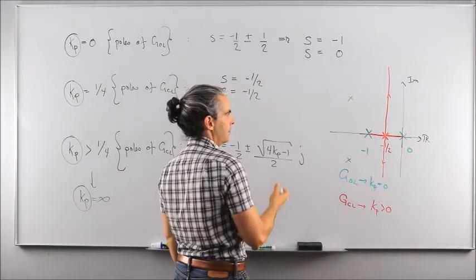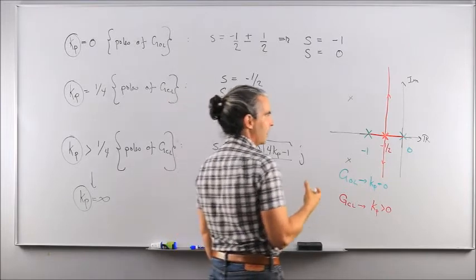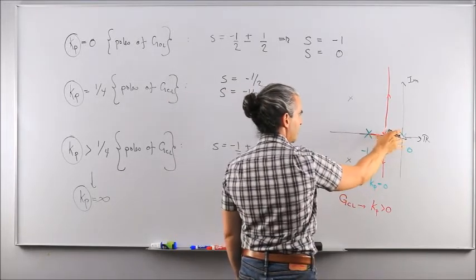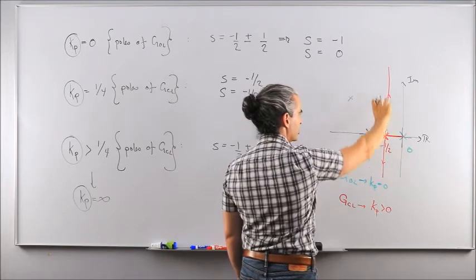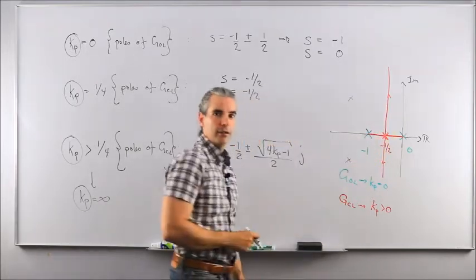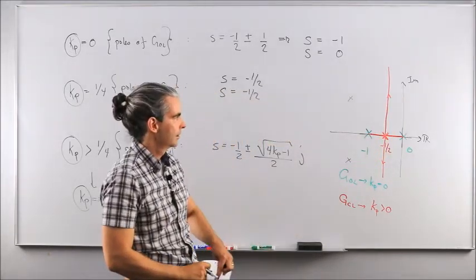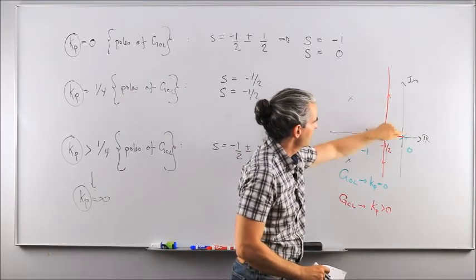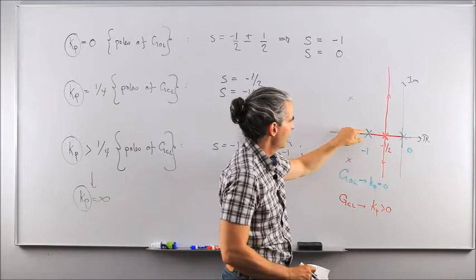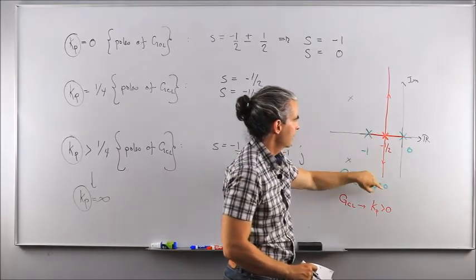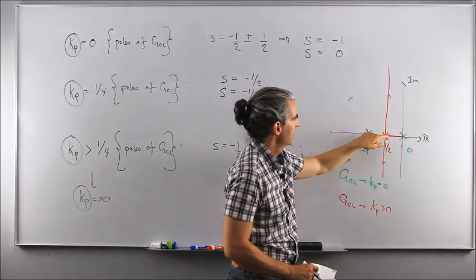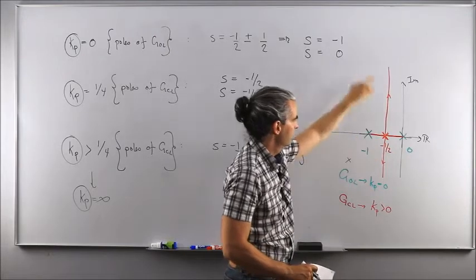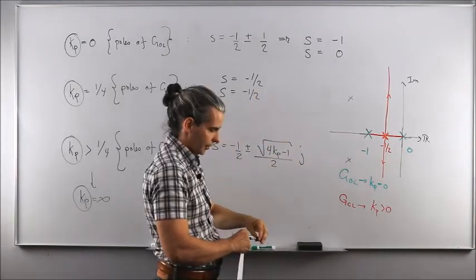But I know that based on the system I have, that would be impossible, because the natural behavior of the pole locations in the complex plane with the controller I have in place is giving me this. So the only allowable positions for my poles in the complex plane are the map I've drawn, right? Or the routes I have drawn here.